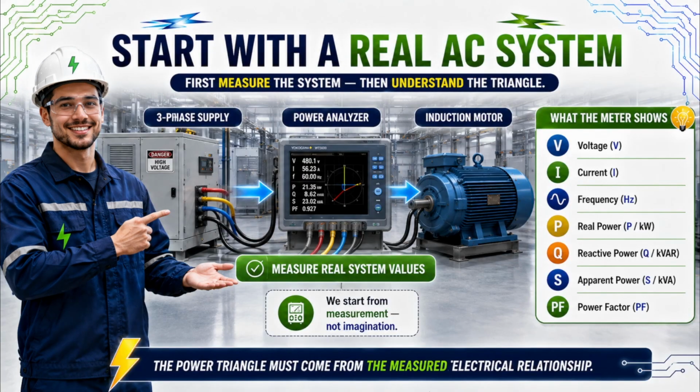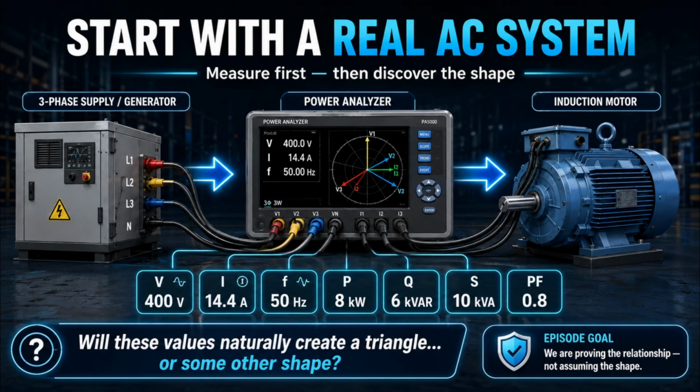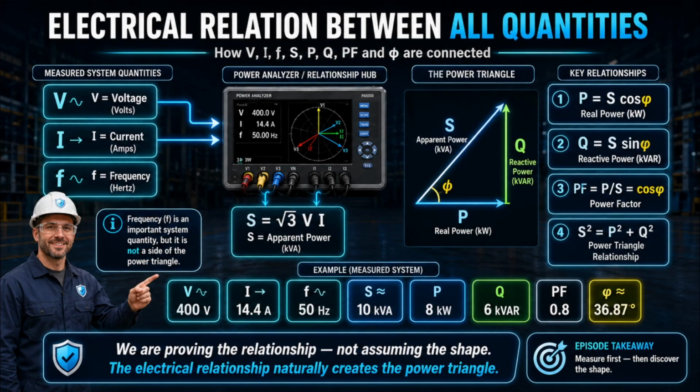Now let's move to a real AC system. Here we have a three-phase supply, a power analyzer, and an induction motor. Suppose the analyzer shows 400 volts, 14.4 amps, 50 hertz, 8 kilowatts, 6 kVAR, 10 kVA, and a power factor of 0.8. We'll use these measured values to see how the quantities are related and find out whether the electrical relationship naturally creates a triangle or some other shape.